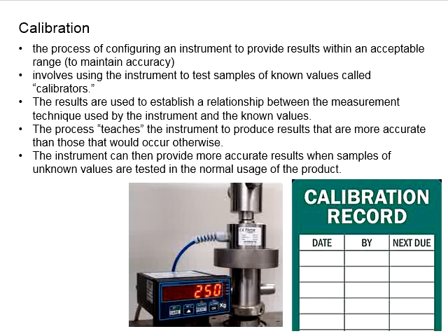For example, you have a load cell with a capacity of 300 kN. You're not sure, or you just want to confirm the accuracy of the reading. You can put some weight onto the load cell, probably carefully stand on the load cell, as you know your own weight, and observe the reading. Is the reading correct? To which degree is the accuracy?